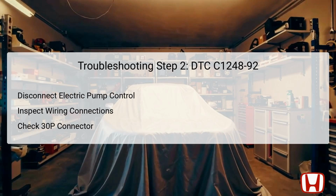For the second troubleshooting step concerning DTC C1248-92, it is vital to disconnect the electric vacuum pump control unit, specifically the 30P connector. This action isolates the electric pump control system, facilitating a focused inspection. Examine both the electric vacuum pump control unit female terminals and the connections for any damage, corrosion, or loose fits. The integrity of these connections is critical to ensure proper electrical signaling.